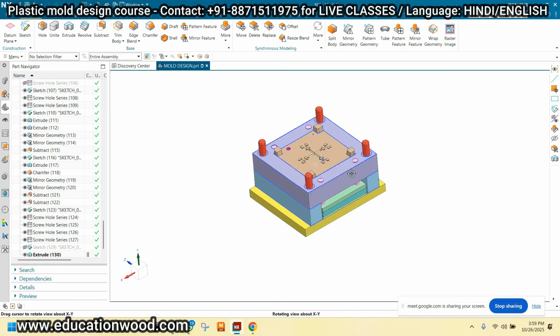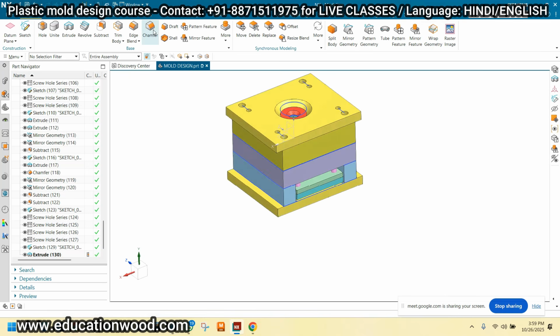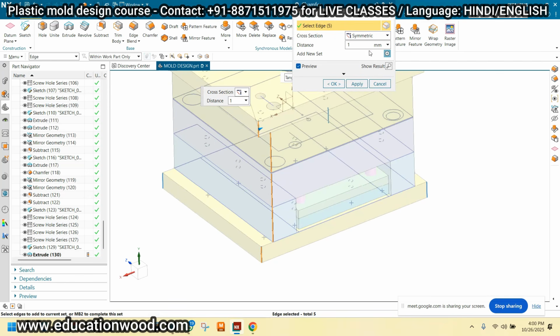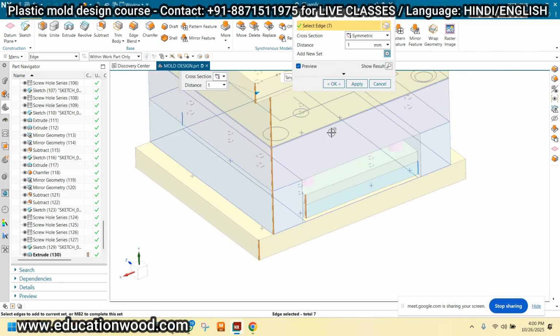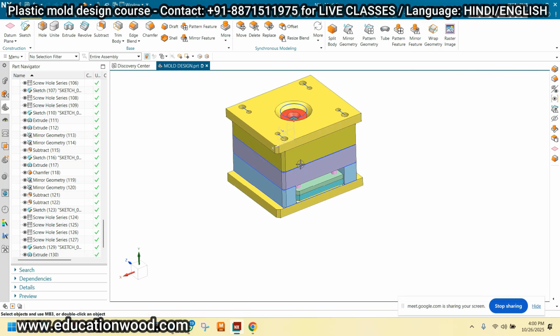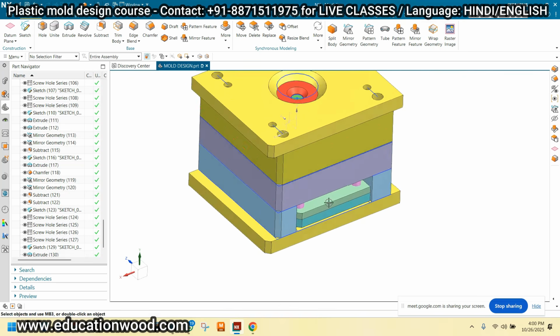Okay. Now, one more thing, reference cut. So what is the purpose of reference cut? Like I'm providing the reference cut. Yes. So for the proper aligning of the molding or the complete mold plates, we have to provide a reference cut. This is only one side, single side, right? This is the reference cut.